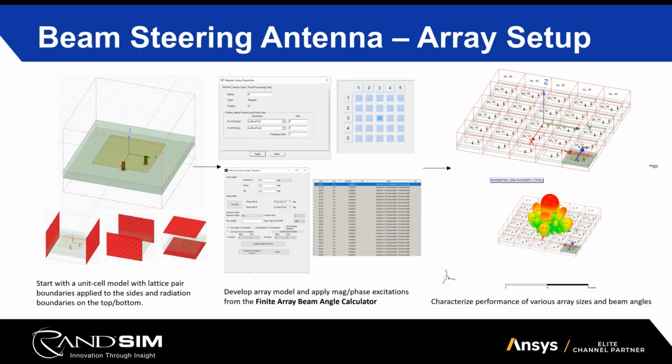All right, so back to our individual patch for a moment here. I kind of want to go through a little bit of a case study process and show off some of the more millimeter wave focused considerations inside of the 5G space for antennas. When we talk about millimeter wave, a couple of common buzzwords would be directional antennas, beam steering, multi-beam antennas, active steering. These things all translate back down to that fundamental aspect of we want to push the maximum amount of data between the devices as we can.